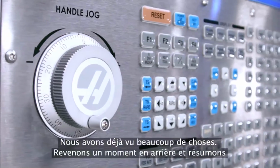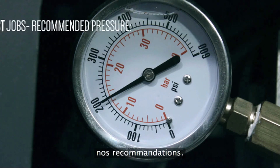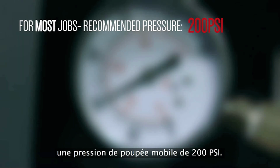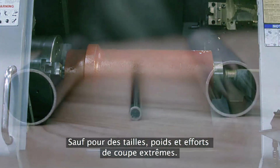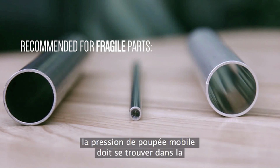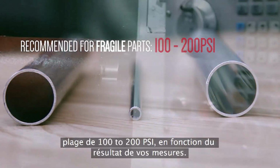We've covered a lot. Let's look back for a moment and summarize our recommendations. For most turning jobs, we recommend starting with a tailstock pressure of 200 psi, except at extremes of part size, weight, and cutting load. When your workpiece is very slender or made from weak material, tailstock pressure should be run in the 100 to 200 psi range based on your measurements.